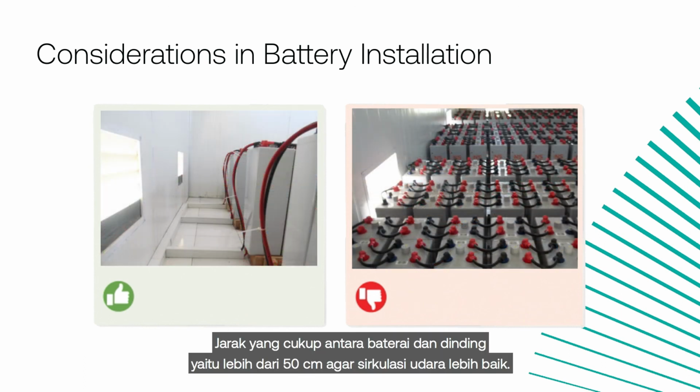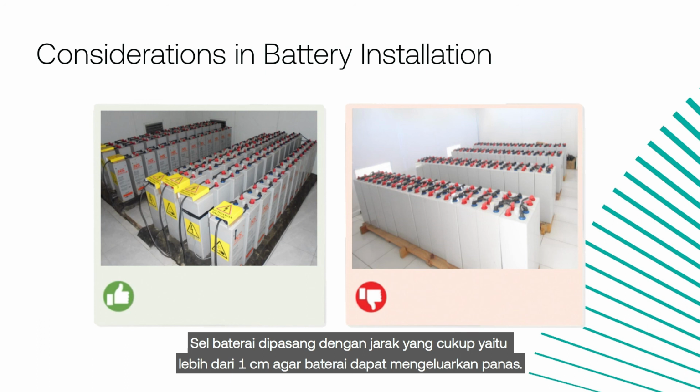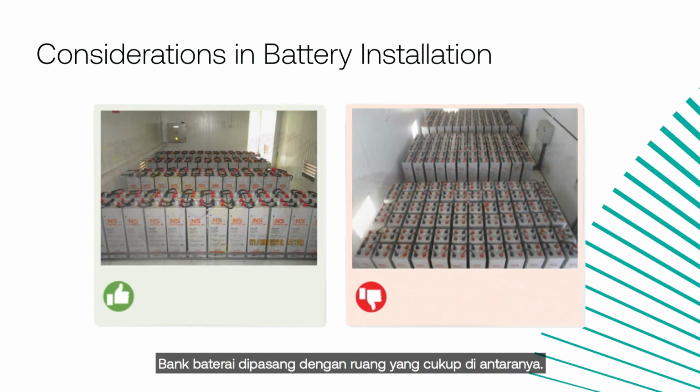Keep enough distance between the battery and the wall, more than 50 cm, for better airflow. Battery cells are installed with sufficient distance, more than 1 cm, so that the battery can release heat. A battery bank is installed with sufficient space between the battery arrays.